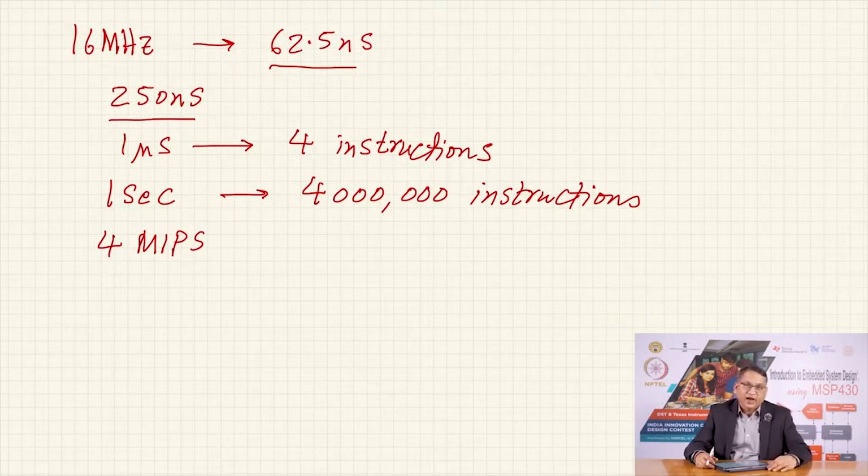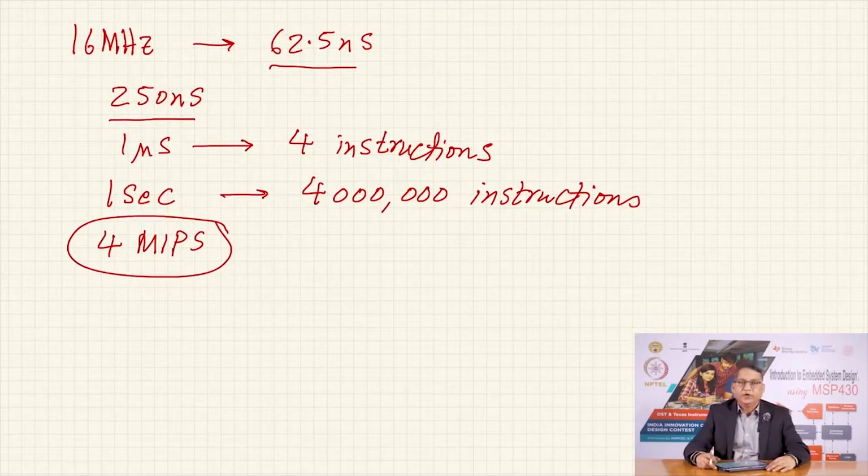Human interaction on the other hand, the act of pressing a switch and releasing it, is a much slower process, which means if a human is going to press a few switches, at this rate the microcontroller will be able to scan and poll many switches in 1 second. Even so, you would be deprived of executing the actual program while the microcontroller is waiting for a switch to be pressed, and therefore, this idea of interrupt is brought into the picture.